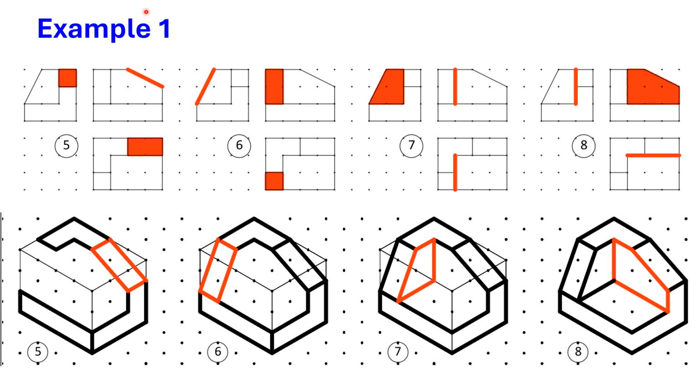Now let us go to the inclined surface, let us say I consider this inclined line. Wherever an inclined line is there, it belongs to an inclined surface. Now this inclined line represents the inclined surface. So this inclined surface is coinciding exactly. If I draw in the top view, it is coinciding with this. That is, this is the one inclined surface. And in the side view, the same inclined surface is visible here like this.